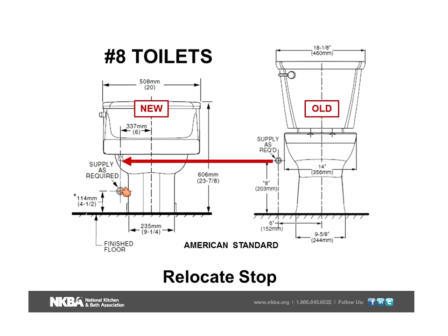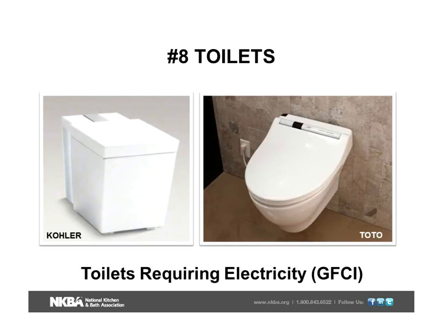Now, sometimes it has to be increased in size slightly. That's not the problem. It's that this customer has marble on the wall that has been there for 40 years. And you're going to try to get that stop lowered down. Now, you might be okay. Maybe the new toilet's going to cover up the old hole. You might get away with that, but it does have to be lowered. So be very careful when you're swapping existing toilets for low-profile one-piece toilets.